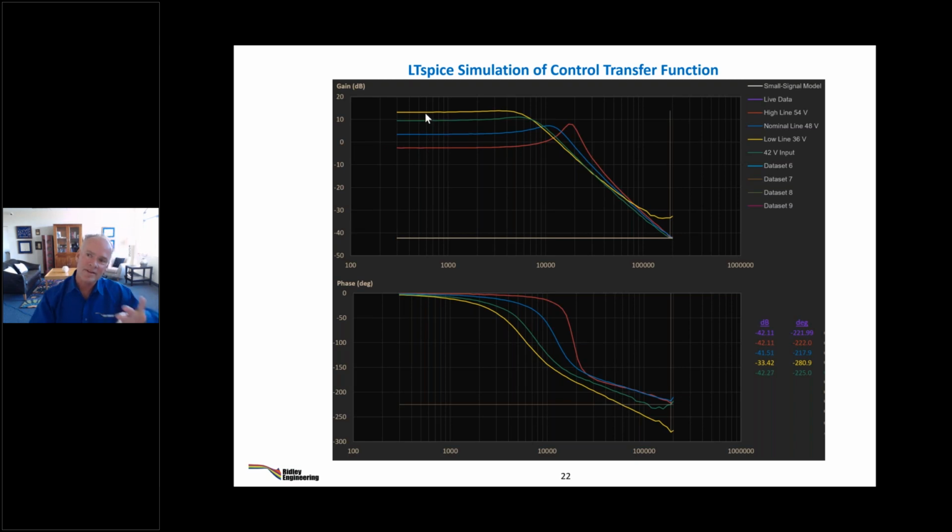And now this gets us back to the gain curves of the LLC, where it's really steep when you're near the peak, and then it flattens out as you get to that second resonance. So that's reflected in this part of the curve here. So this is an entire topic unto itself. And then, of course, you're only just starting when you look at the control to output of the LLC.